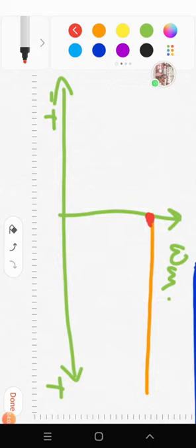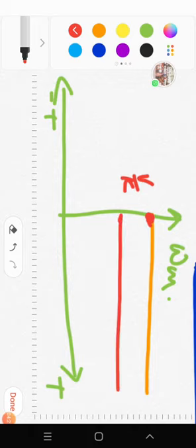So as we change V, this point V by K will be shifting. So we will get some shift in the characteristic. So for V by K it is a natural characteristic, this is no load speed.